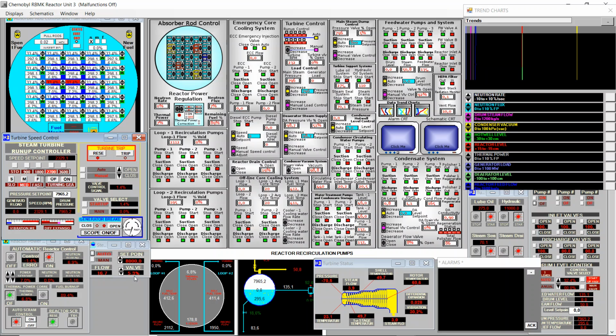The relief valve is at 5.3%, so I will close a bit more. I will reduce a bit more the power set point, 6.5%, to see if we can get close to 0, just to save energy. We got a bit of vibration now. It seems that the shell cooled down more than the rotor.